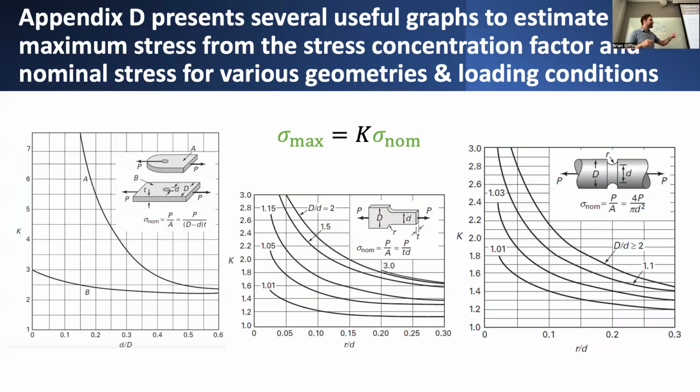So in those cases, you could maybe even use superposition. If there's some combination of loading under axial, bending and twisting, you could superimpose those solutions and figure out the resulting maximum stress combining all those things. So possibly quite useful, but things to keep in mind. In any case, the homework problem on this should be relatively straightforward to do. Hopefully that gives you some confidence.